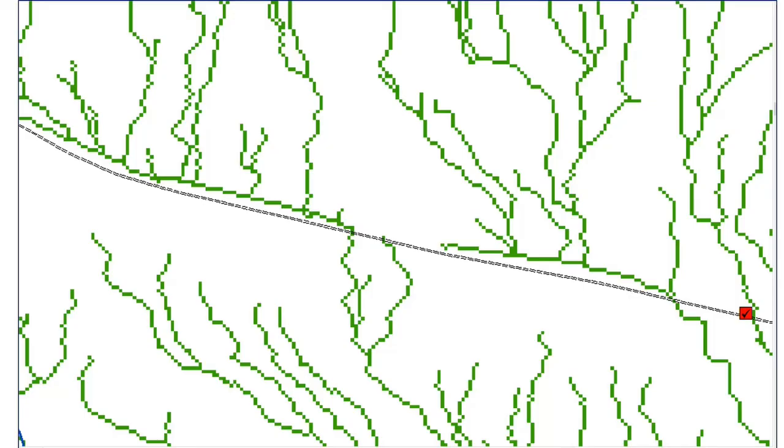Here's an example where we have a road with a ditch. The ditch is on the north side of the road, and we filled it in, but sometimes filling in sinks overfills areas. And so we have a situation where water is now in our digital elevation model spilling over the road where it's not supposed to because we filled it in.